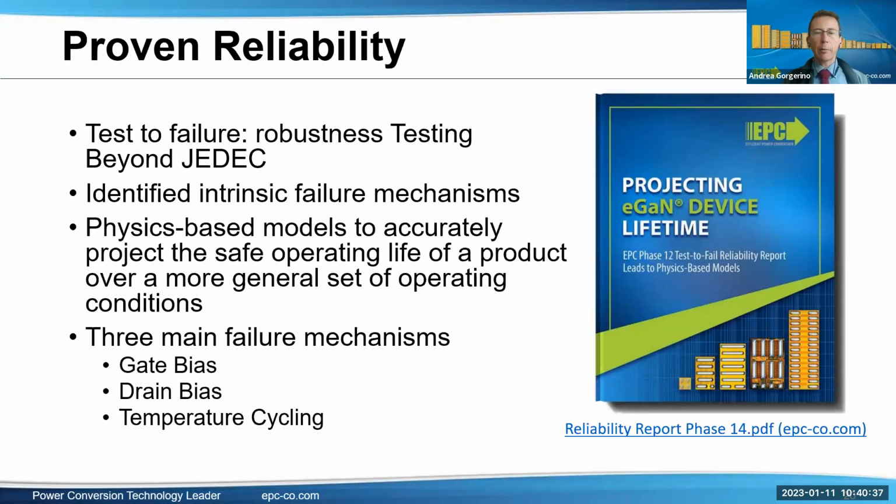So ringing, for example, and reverse recovery is another big contributor to EMI. Of course, there is a component of the spectrum being generated during switching events, which naturally is proportional to the dV/dt and the dI/dt. But more so, these other elements are big contributors.